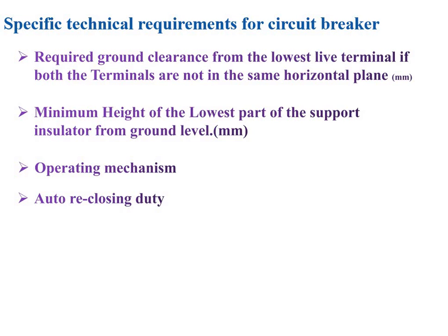But if the fault is temporary, it should not remain in trip position or open position continuously. So for that purpose, to identify the type of fault, whether it is a persistent fault or a temporary fault, we can go for the reclosing of the circuit breaker.